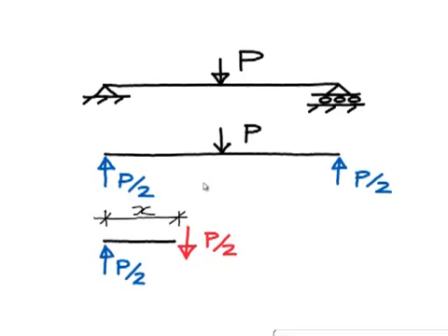It's going to spin. It's going to spin in a clockwise direction, and therefore we know that at the cut there must be a moment acting which will, as it were, spin that free body back in an anti-clockwise direction. So we'll call that moment M, and in fact that is a bending moment at that cut. That is the moment, the internal moment, which must exist at that cut to maintain equilibrium.